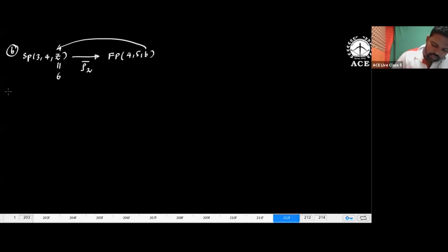So what is H2 here? H2 is equal to I by 2 pi rho. I'll directly write 10 by 2 pi into current direction z cap cross vector. Perpendicular vector is 4 minus 3, here it is x cap plus y cap, divided by its magnitude, square root of 1 plus 1, whole square.